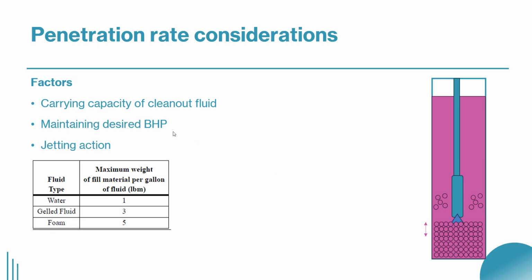So always consider the bottom hole pressure, and don't load your well with proppant unless you make a calculation to make sure that the equivalent density and the equivalent hydrostatic pressure will not induce losses in your formation.